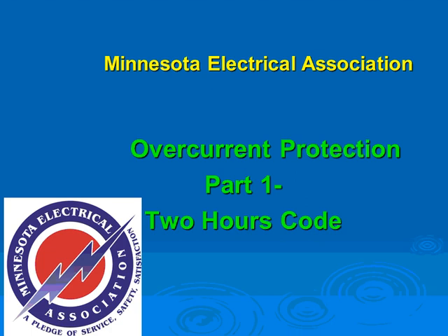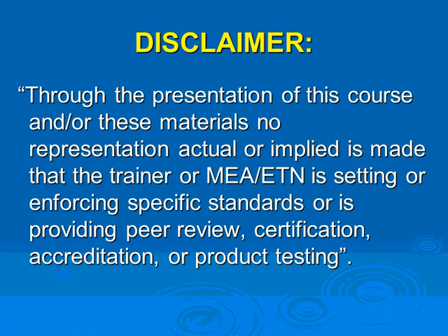With all this said, the major factor protecting you, especially from the shock hazard as well as the arc flash hazard, is the overcurrent protection devices in your power system. That's it. Without the overcurrent protection devices, your switchgear is nothing but a bunch of wire nuts and bolts and so forth. It would not protect you from anything in any shape or form. So that's why we picked, guys, the NEC code book, Article 240, which covers overcurrent protection devices.